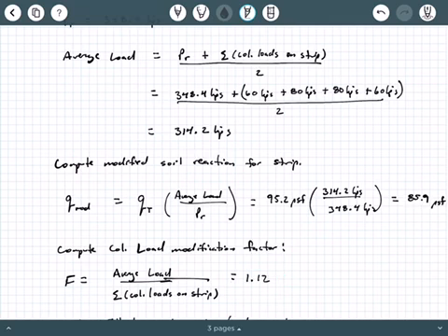And again, I want to emphasize why we're doing this, because it seems a little silly. Why are we doing all these calculations? The reason is that when you're analyzing a strip, you're not capturing what is happening in the vicinity where adjacent strips are touching each other, specifically in regards to shear force.